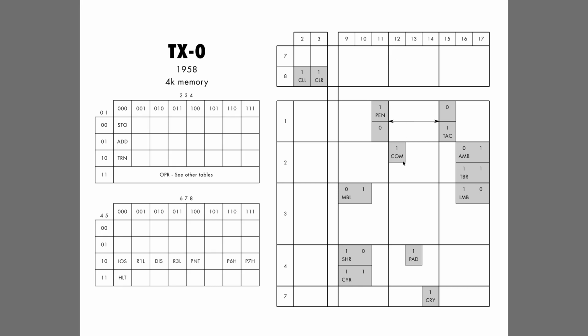So if now we combine these 3 bits in a single instruction, we see that at time pulse 8 cycle 0, the full accumulator is cleared to zeros, and then at TP2 it is complemented, giving all ones, or -0 in one's complement. So you can see that this is quite useful, because if you do it before a transfer of negative, that gives you an unconditional transfer, because the accumulator is guaranteed to be negative.